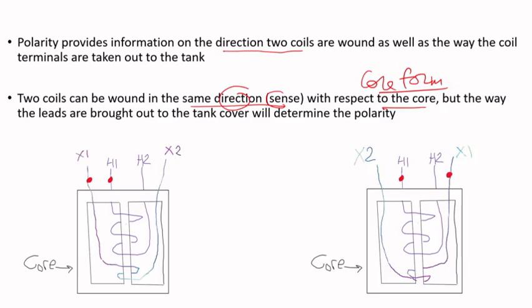The coils are concentric. In other words, you have the core, then the low voltage is wound around the core leg, then the high voltage on top of the low voltage, and so on. If you look at the high voltage, for instance, let's get a highlighter.